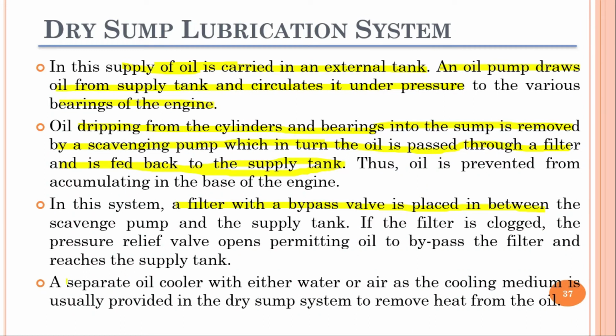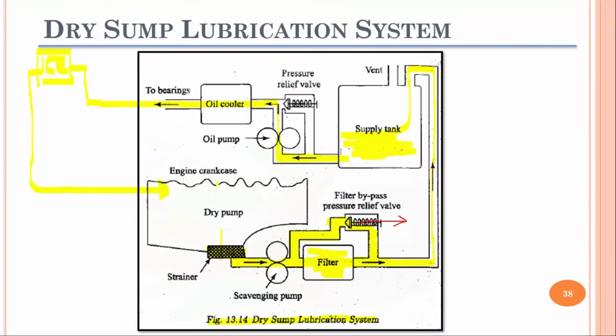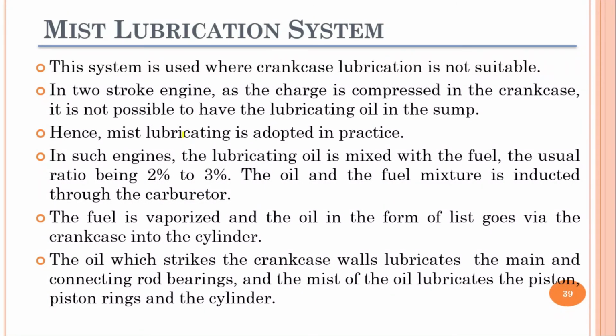And we have a separate oil cooler with either water or air as a cooling medium, and it is usually provided in the dry sump system to remove the heat from the oil. I hope all of you have understood the basic concepts of the wet sump lubrication system and dry sump lubrication system. Now moving forward to the last type of lubrication system, and that is the mist lubrication system.